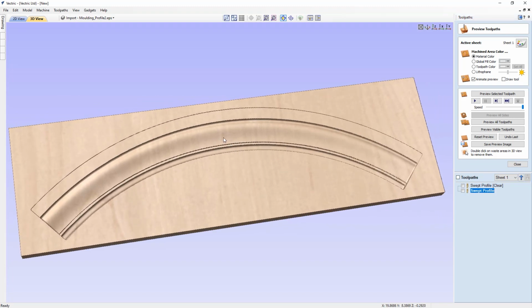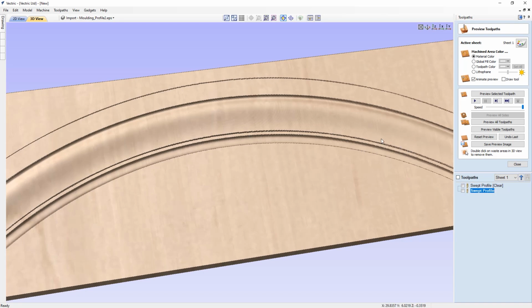Now this looks like a really nice toolpath, because the way our tool will actually follow along that vector arc that we have, our finish will be really nice and clean. Any machining lines that we have will actually follow this arc, which means they may not even be noticeable, or they'll be easily sanded out to blend in really nicely.